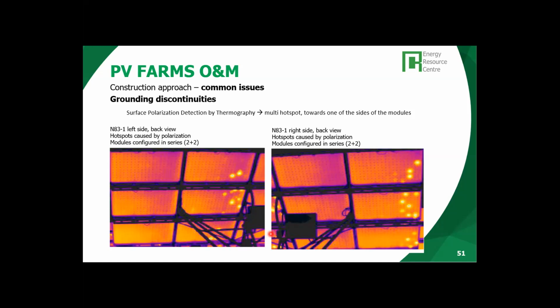In this case, the problem was solved not by repairing the earthing, because it's very difficult to find the general problem, but by injecting an inverse current through the DC lines opposite to this polarization. The energy cost of this intervention represented more or less 0.5% in front of the 5% of the loss that was occurring. It was solved, but it was interesting to find the problem. I don't know if it's possible in another plant, but in this case it was evident.